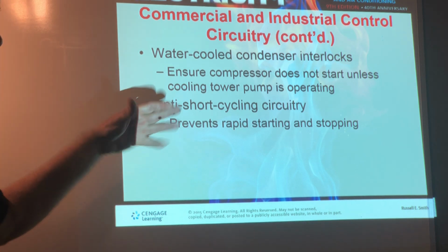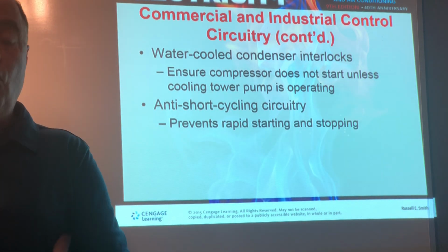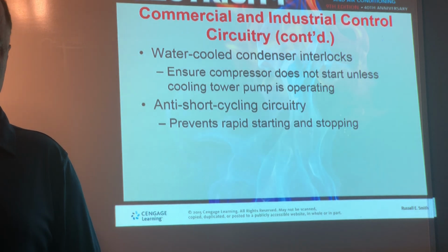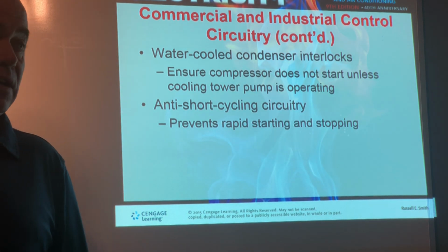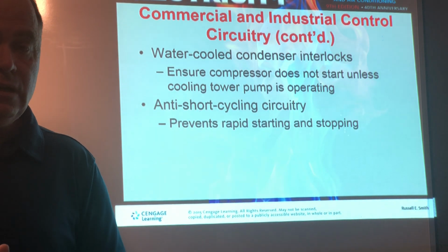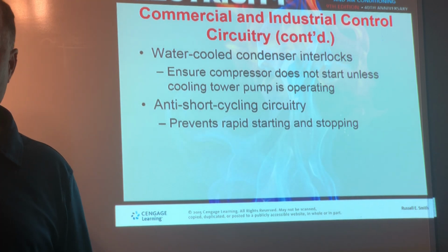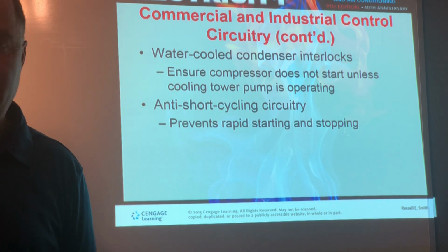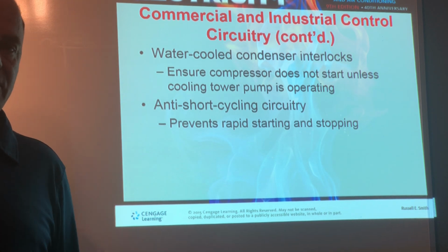And again, with any system, anti-short cycling has actually gotten more and more pervasive over the years. And one of my, which I should create my 10 commandments, is once an air conditioning or refrigeration compressor shuts off, don't ever restart it for any reason for 2 or 3 minutes. You trip over a cord, you unplug something, don't plug it right back in. Let the pressures equalize as much as possible. Let that compressor cool off.